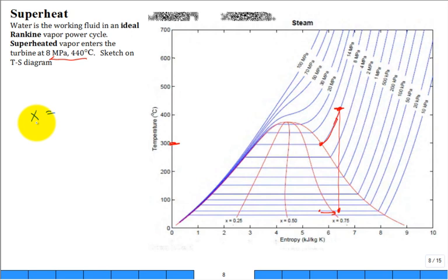Now, how does water as a two-phase mixture go out of a steam turbine at a high rate of speed? Well, it's going to come out like a fog. And what happens is the little water molecules coalesce and they bind up and they become little droplets. A thicker fog, bigger droplets. And so when it's flowing out, those little droplets, think about the mass density in that little droplet compared to the mass density in the vapor that's around it.